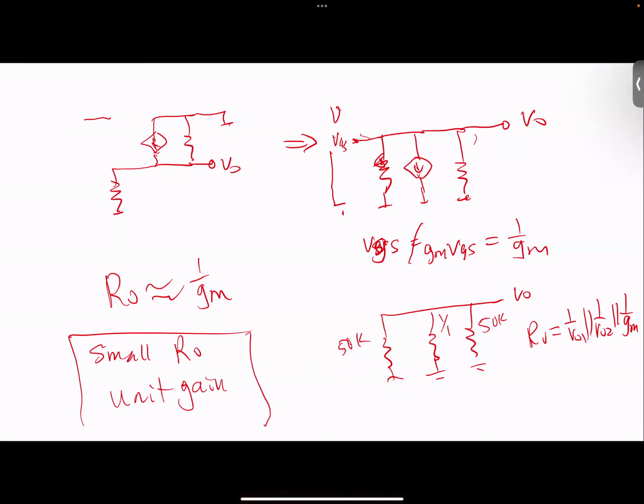So by this time, I think some of you might already get confused. Earlier you said you want to increase the output resistance. So now you want to reduce the output resistance. What's the point? What are you doing? Well, the previous one, we tried to increase output resistance, we use that thing as a load. Here we decrease the output resistance because we used it as amplifier.